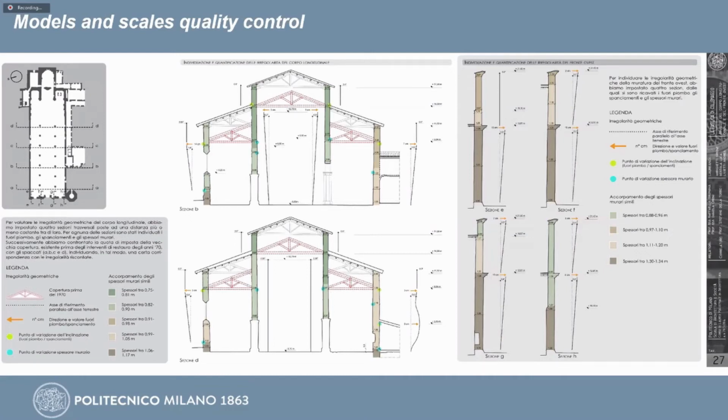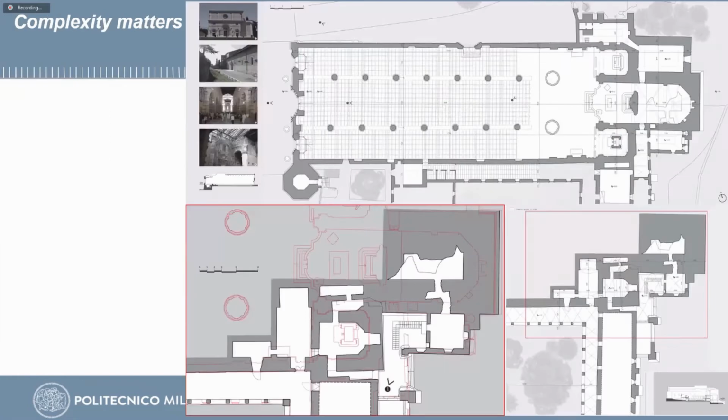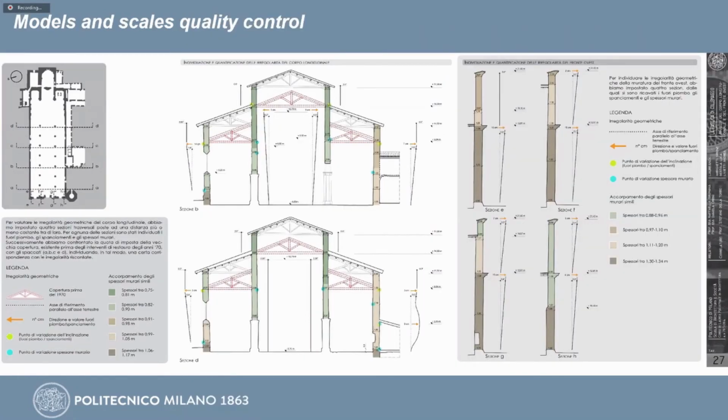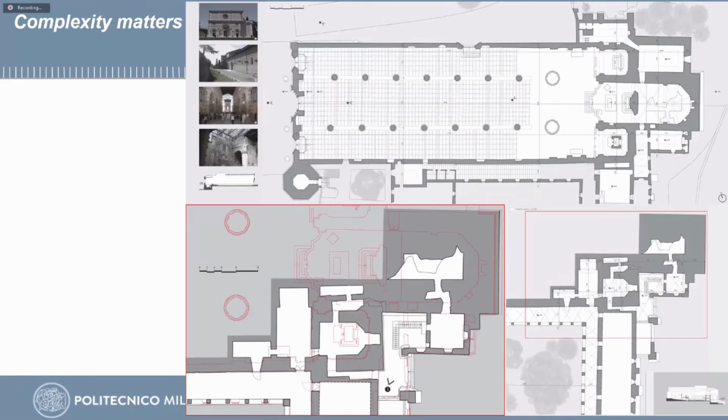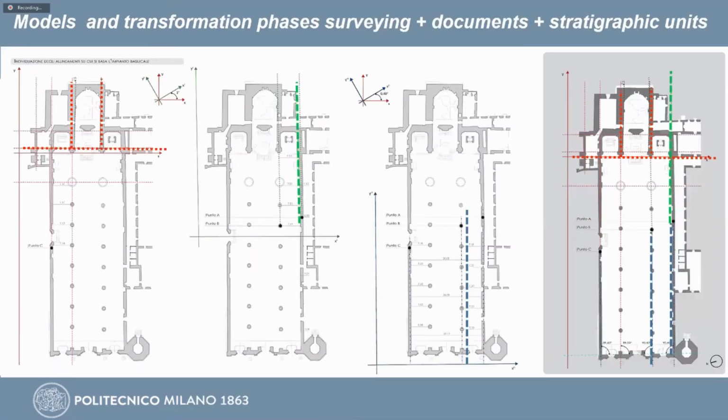During the earthquake, the dome crashed, and all the surveying has been addressed to detect the out of plumb with a high accuracy corresponding to the scale 1 to 20. That's to say, with 4 millimeters of tolerance with the laser scans. All of these data coming from the out of plumb and from the highlighted sections revealed perhaps the false structure of the underground level with respect to the area of the altars.